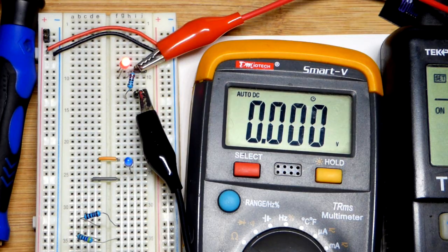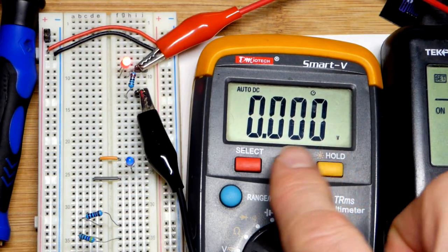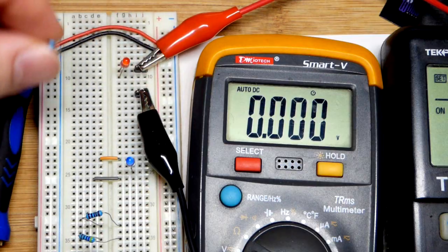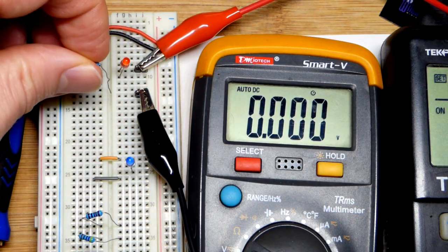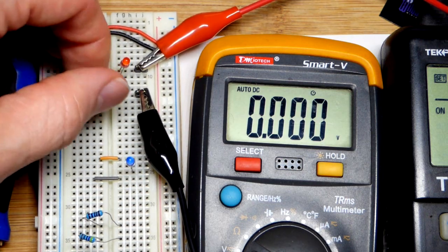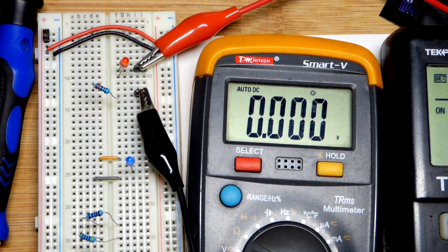So now, when it comes to measuring current, we have to be more careful. So we have the multimeter set to measure voltage. It's good to keep it doing that. We need to open up the circuit. These resistors do get hot, so you know it's not hot right now, but just be aware of that. So best to turn the power off, let the resistor cool down before you handle it.